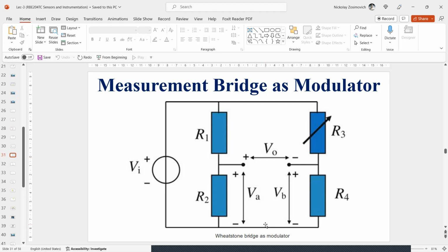Modulation techniques also apply to many non-electric signals, and optical signals can be modulated using an LED or laser diode. If our source itself cannot be modulated, optical modulation can be performed by, for instance, a chopping wheel, as is applied in many pyroelectric measurement systems. And also, some magnetic sensors employ the modulation principle too.